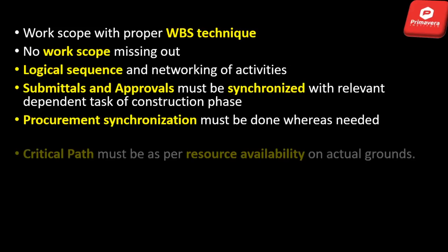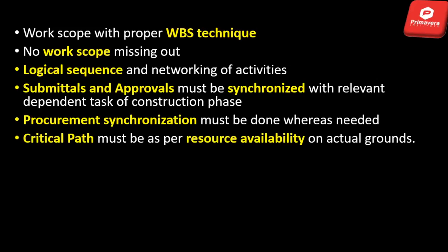And then the critical path must be as per resource availability on actual grounds. This is a very, very important point, because the critical path is the time management key point. Your project time is controlled by the critical path developed during your planning phase. So this course, delay analysis and claims management, also belongs to the critical path. So your critical path should be very realistic.